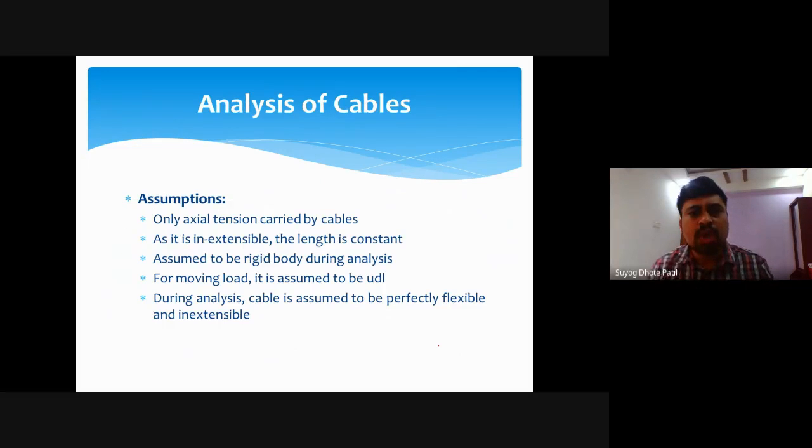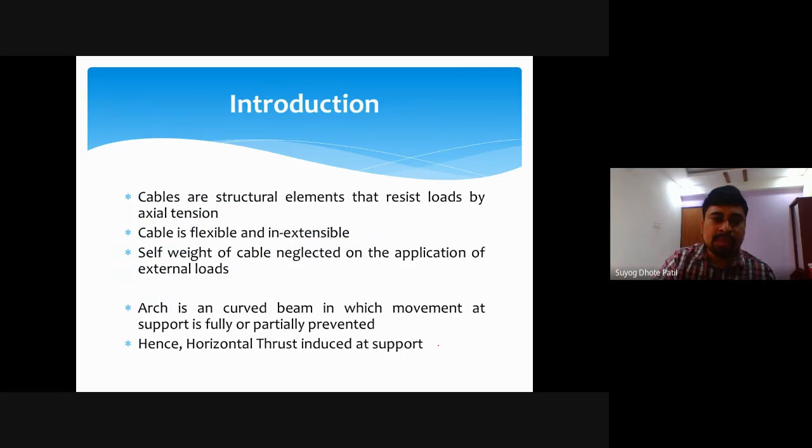Now, analysis of cables. The basic assumptions we have seen earlier, but we will see them again. Only axial tension is carried by the cable. It is inextensible, that is, its length is constant. It is assumed to be a rigid body during analysis, though it is a flexible member.